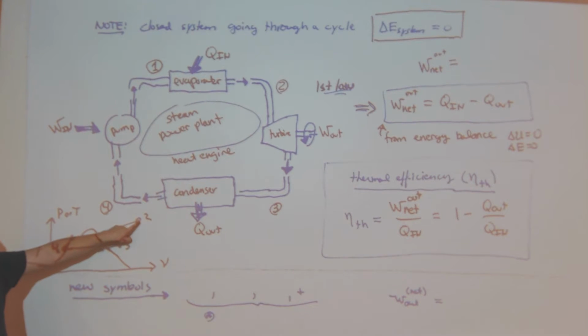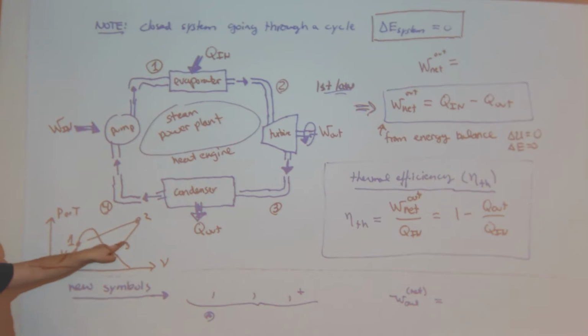Through the turbine, you go from superheated steam to another type of steam. Of course, state 3 could be anywhere down here or within here, but I just put it out here, so now I still have superheated steam. Then the condenser converts all the steam to liquid, and then the pump brings it back up again. And there's an area in this curve, of course, and if I look at it, it's clockwise, so that's work by the system.